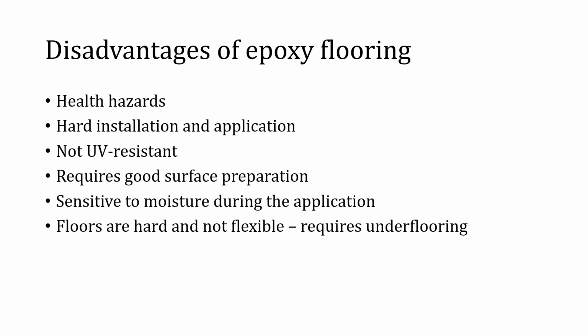Using the wrong type of resinous floor systems for a mismatched environment can result in floor failure and ultimately substrate harm. Epoxy floors are hard and therefore there is a contact noise during walking. For this reason, flexible polyurethane floors are usually used in office spaces and homes. Also, without underfloor heating, an epoxy floor feels somewhat cold, similar to tiled floors.